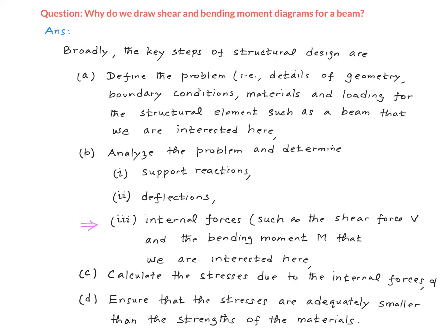Since we don't know exactly what the maximum shear force and the bending moment are and where exactly those are going to happen, what we do is we try to plot the distribution of the shear force and the bending moment along the length of the beam. Then by looking at this diagram, we will know exactly where the maximum shear force occurs, where the bending moment occurs, and exactly what those values are.